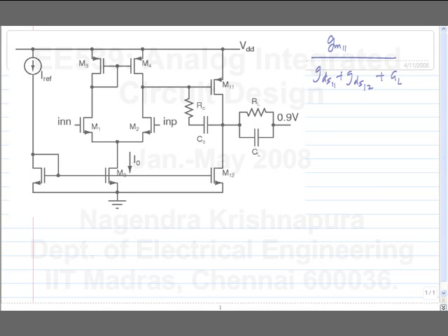So, the good thing about this particular stage, which has a common source amplifier and a current source, that is one transistor on each side to the supply, is that it can support a large swing. If you have a gain of 1, that means that the swing at this point is the same, which the previous stage cannot support. Okay, you will not be able to use the full swing. So, ideally you should design it so that this will give you the full swing, VDD minus 2 VD sat, and the gain is enough so that the previous stage is operating properly with the output swing divided by the gain. Okay. So, the gain may be like 5 or 10 or something of the sort.